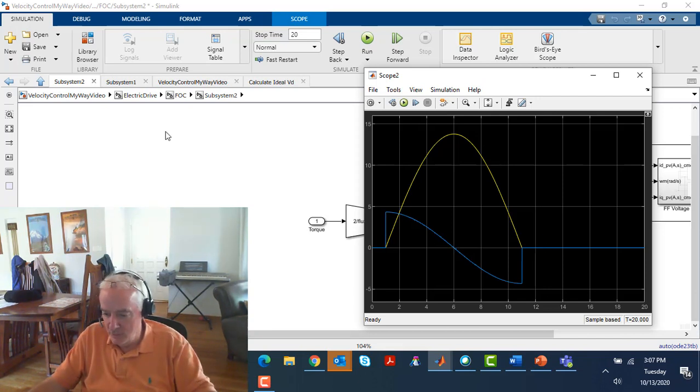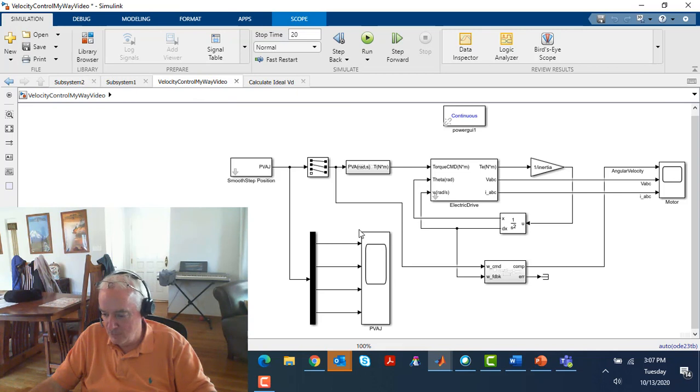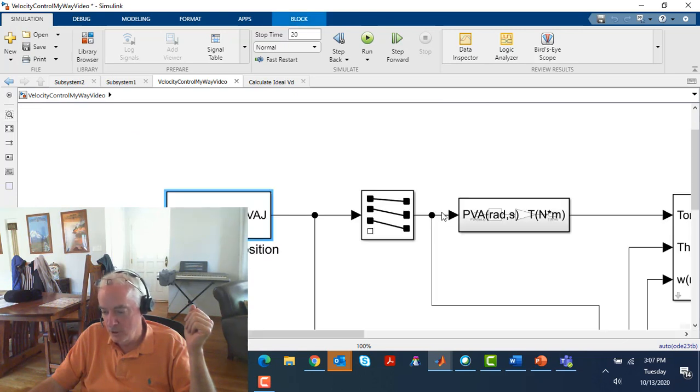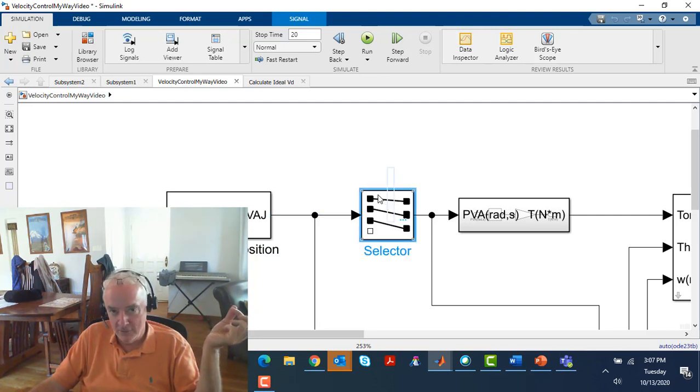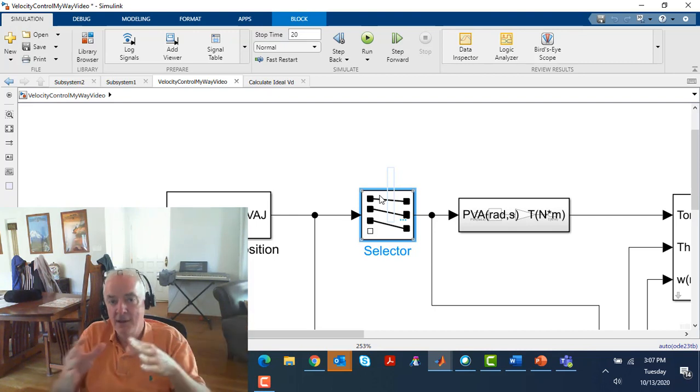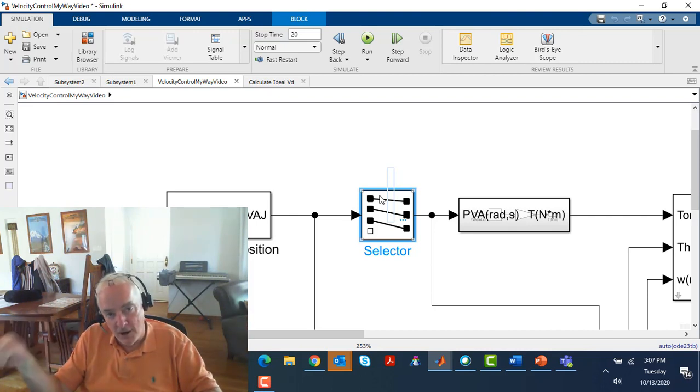And so here's where I just want to wrap up with regard to demonstrating this model, is that the command signal itself that I've sent to make all this work is a 4-component signal. I'm only using 3, which will be essentially, this is a motion command. So I'm commanding motion of the shaft, the velocity of the shaft, the acceleration of the shaft, and then this fourth one would be the jerk of the shaft.